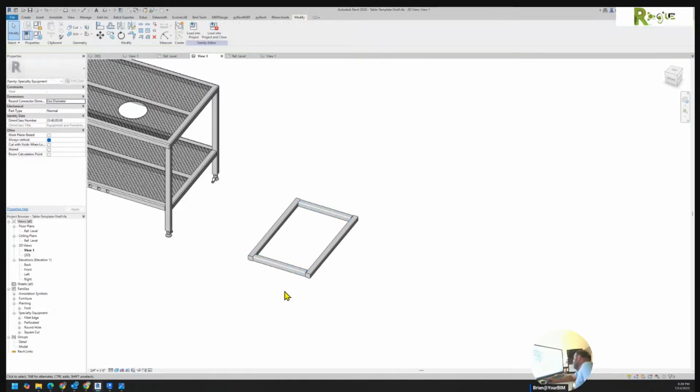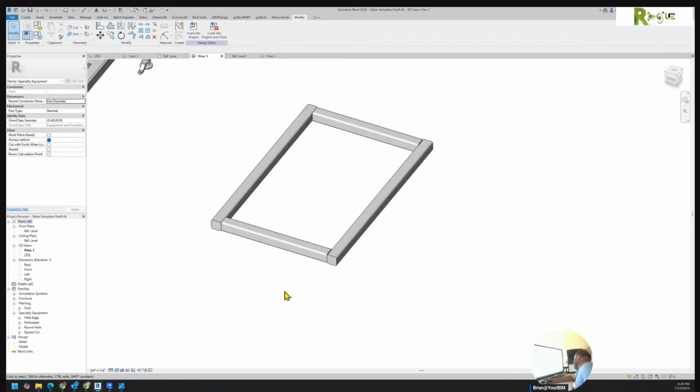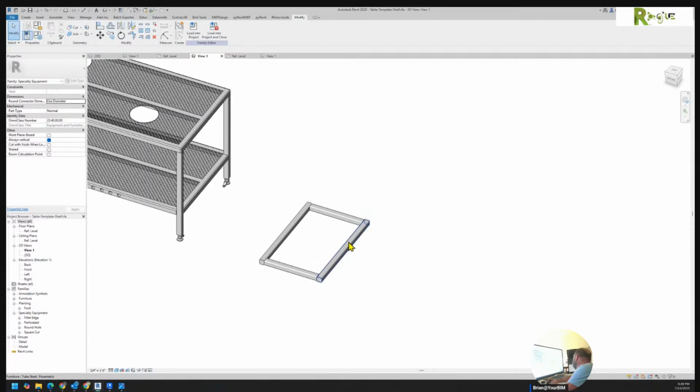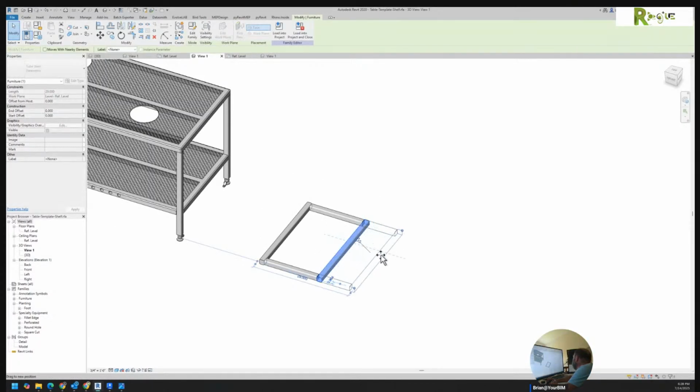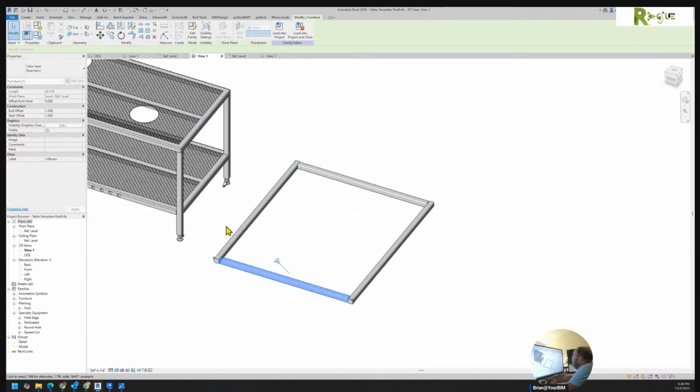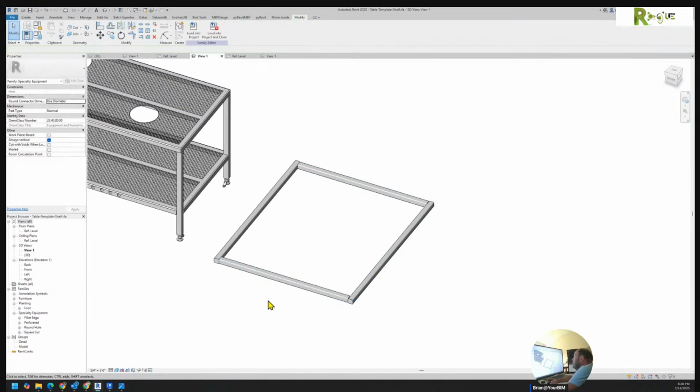Okay? And then I'm going to try to see what the size impact is and whether it's a problem or not. I don't think it will be. But what you don't understand when you're building these line-based families, watch this. If I lock this down, right? If I put a parameter on this, notice what happens to the other two objects. You see that? So all I have to lock down is the 4 lines, and everything else will follow its way through. Okay? That's essentially how I built these.